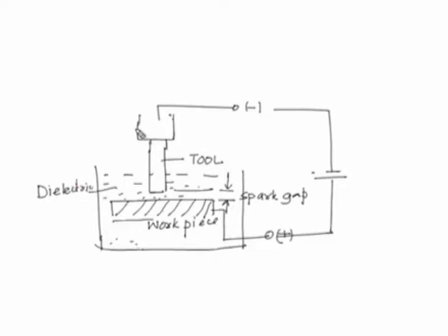This will be continuously kept flowing by some pump arrangement, and this dielectric fluid will take away the debris produced in this zone while the actual machining takes place. These are nothing but the debris, and they will be flushed away by this flowing dielectric fluid.